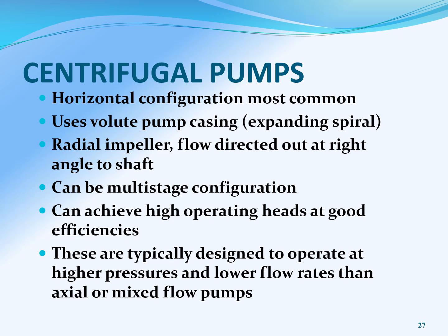Get some more information on centrifugal pumps. They are typically horizontal in configuration. It's the most common setup for a centrifugal type pump. They use the volute, that expanding spiral. They could be multi-stage, which we'll talk about later on. They can achieve high operating heads at good efficiencies. So you're talking like high 80 percentile for efficiencies. And these are designed to operate at a higher pressure with lower flow rates than the axial or mixed pump flow.